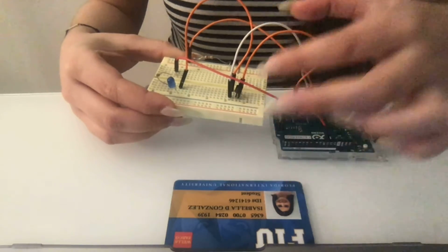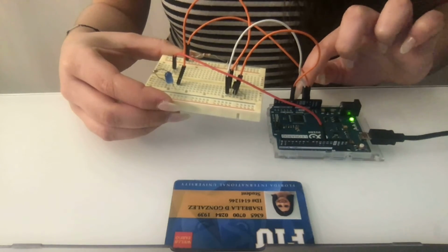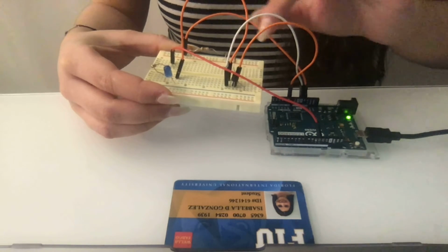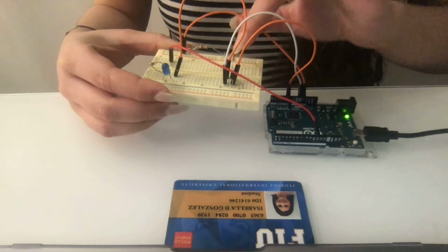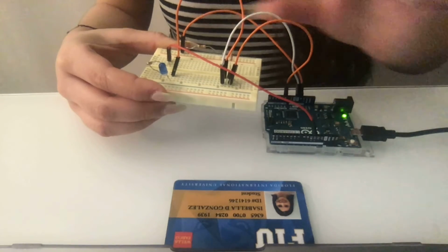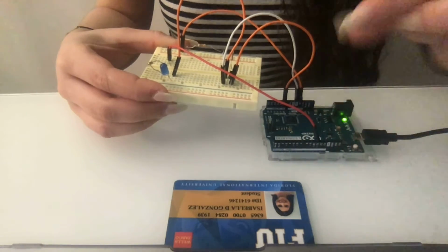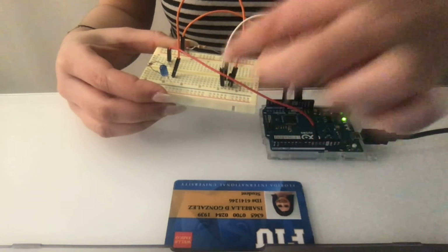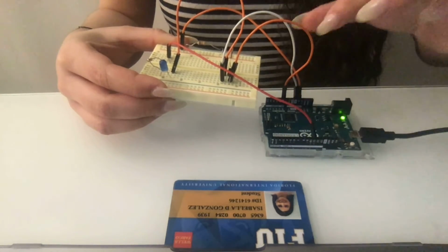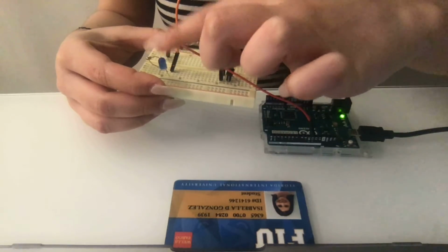This second pin is connected to this orange jumper wire that connects to the analog pin A0 from the Arduino, and it is also connected to these two resistors of 1 kilo ohm each. These two resistors are in series, and then connected to this orange jumper wire that goes to the 5 volt pin from the Arduino. The third pin in my temperature sensor connects to this white jumper wire that goes to the ground in the Arduino, and then this jumper wire that goes to the blue LED diode here.